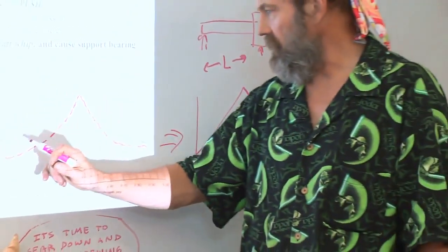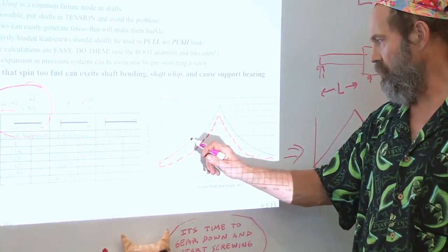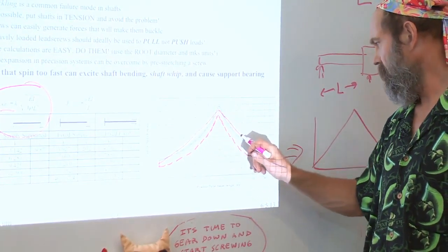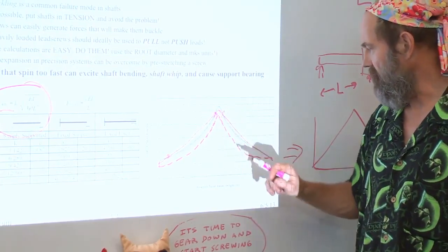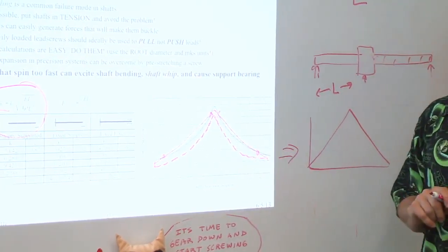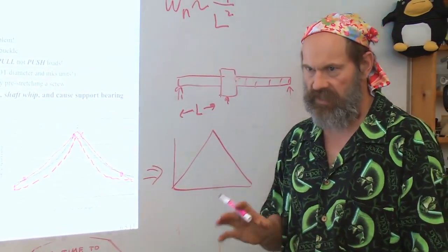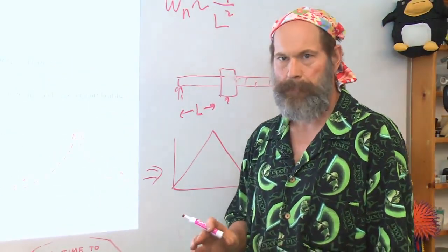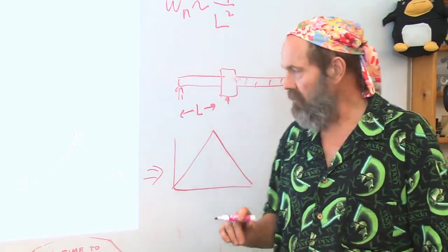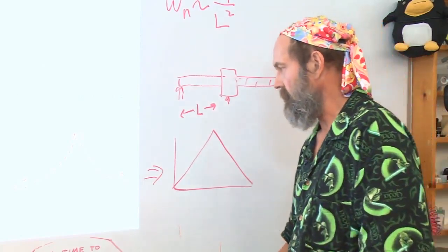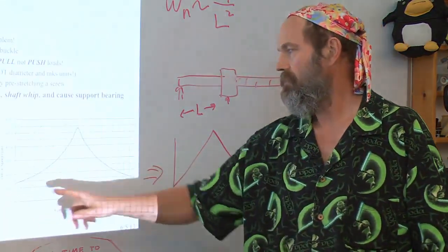What you don't want to do is let your controls people do a true triangular profile, because then you will cross over this critical shaft speed curve 4 times. So you'll start moving and the machine will go, and it'll have these, what was that noise? Is the dog in here? You need to be able to stay below this critical shaft speed.